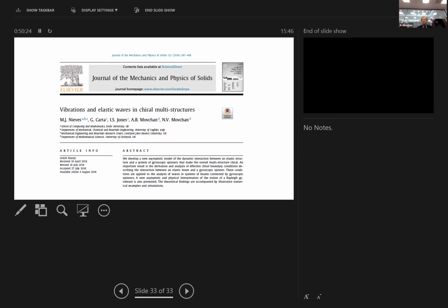And you can even find on YouTube a video with a Chinook helicopter being destroyed deliberately as part of an experiment. The dampers were removed, and on shutdown, it picked up the low frequency resonance corresponding to this resonance for the gyroscope, and it's just gone. If you Google Chinook resonance, you will find it. And it wasn't an accident, it was a pre-designed experiment.